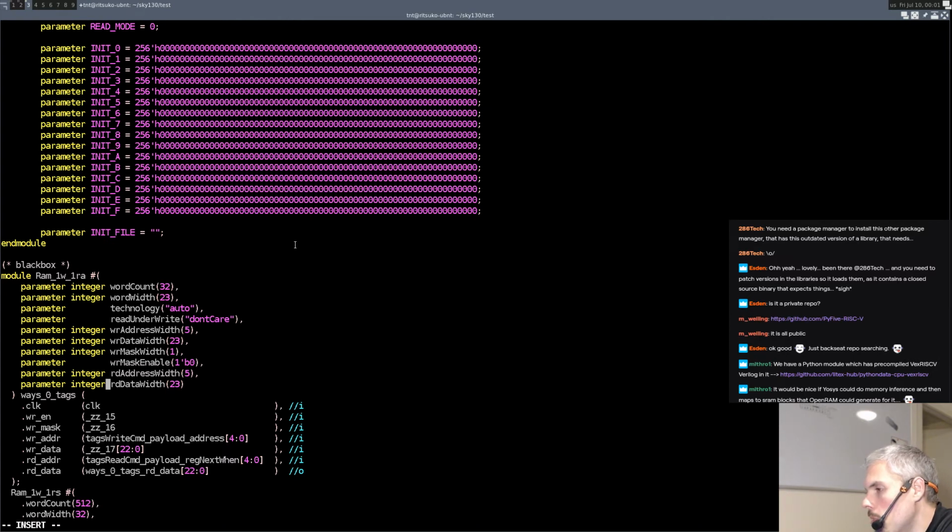But you could map it to something that just leaves it as is, and then look in the netlist, find all the memory cells, including their configuration, and create an OpenRAM configuration for them. The problem is not all configurations of RAM that users can generate will work in OpenRAM. That's the issue, right?